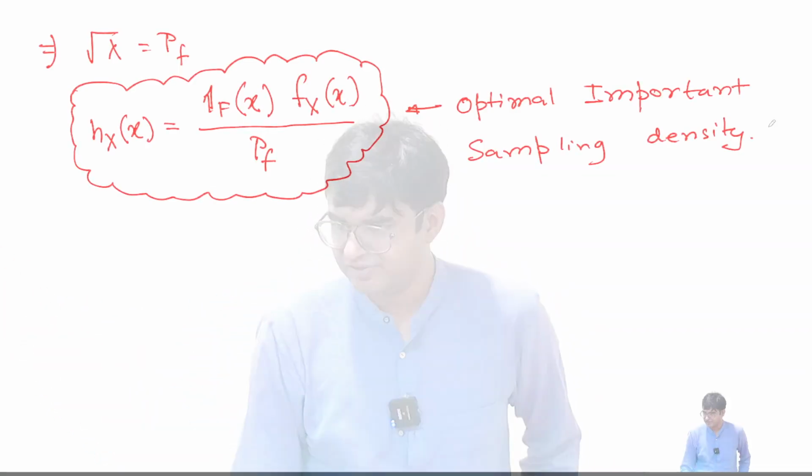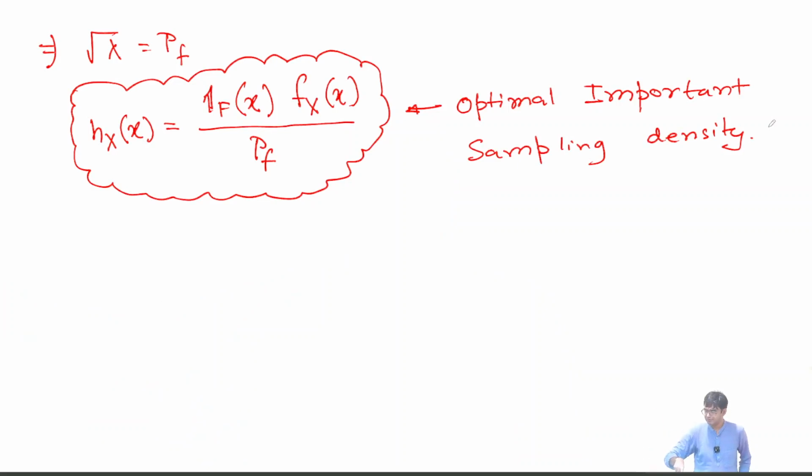Are the samples supposed to lie on the limit state function? When I was talking about IF, was IF always giving you equal to 0? So you are not supposed to have points on the limit state function. Why would you? You are supposed to have points on the failure domain, and you are supposed to have points on the safe domain also, but you want failure points, right?